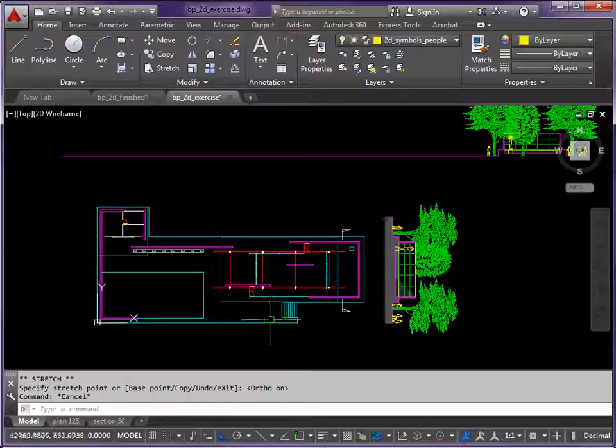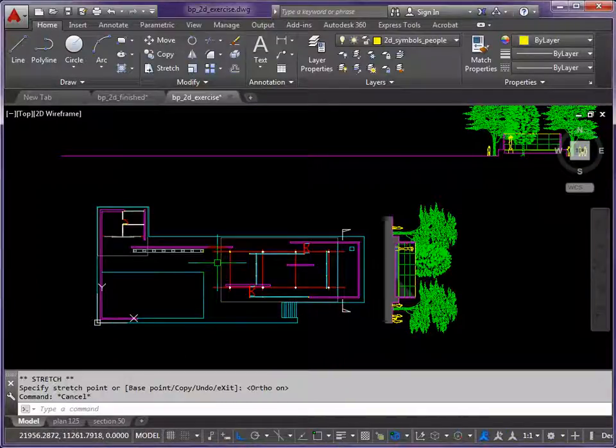The thicker lined objects should be closer to us. And then as the drawing recedes away from our view, we change the line weight to get thinner and thinner towards the back. We'll save the thinnest line for the paneling on this wall, and this wall. Okay, so we can indicate the pattern for the marble panels.